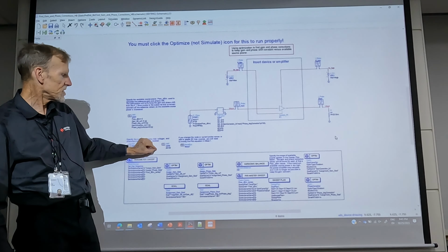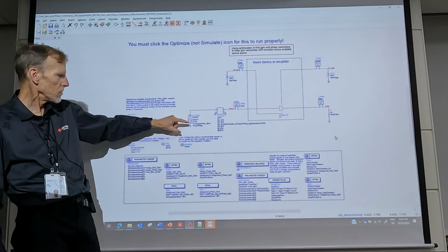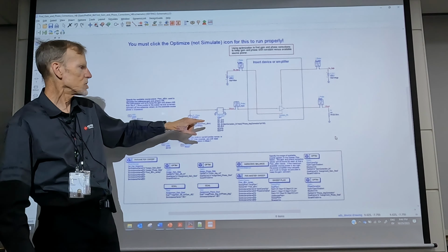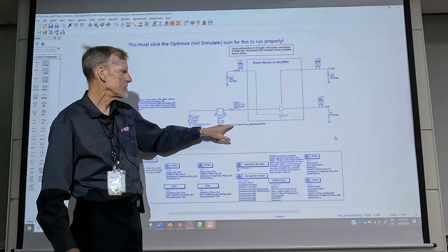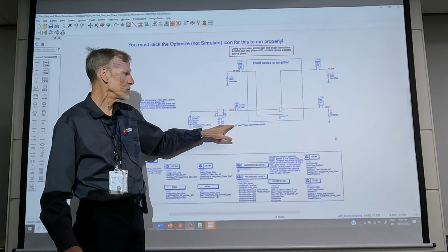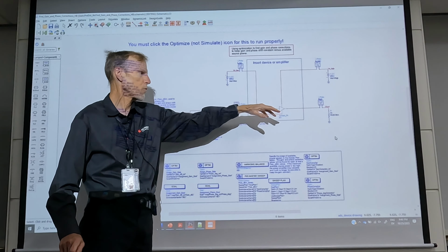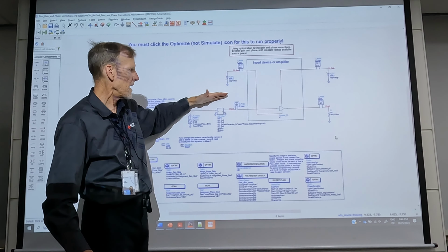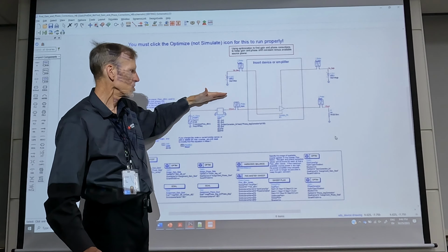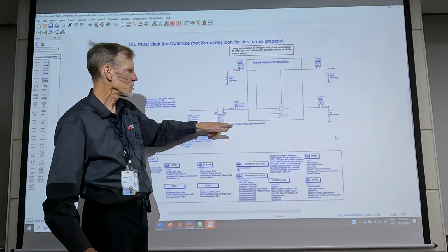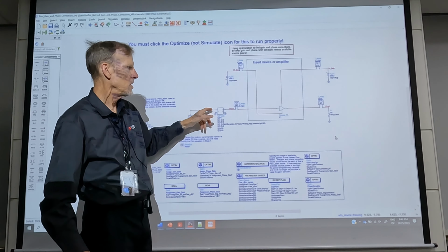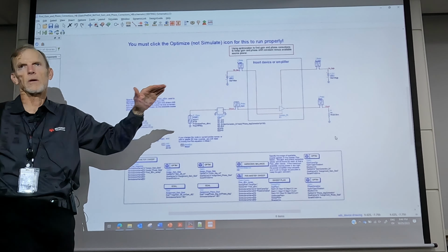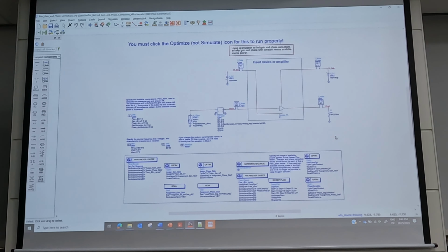And then as we step the source power, we have a source power sweep. During the optimization, we figure out how we need to correct for the gain. The amplifier starts to compress, so we have to basically pre-distort it. We have to apply an additional gain to the signal, as well as a phase shift, such that the gain and phase at the output remain constant. And that's done via optimization.